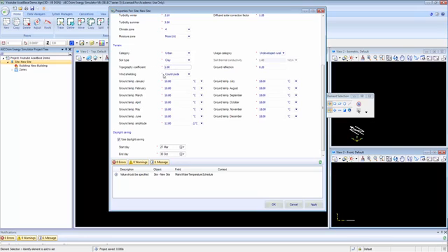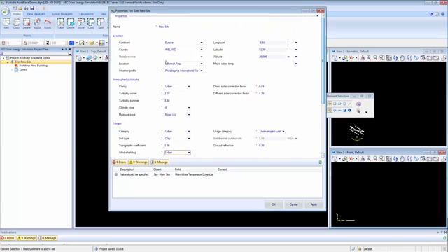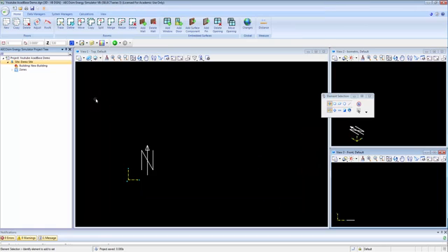Let's see, topography coefficient, wind shielding, countryside. I'm going to go for urban on that. And let's see what else we have. Daylight savings, if you want to set those as well. So there. Just a couple of quick changes there. Site, we can call this demo site, just to give it a name. So again, click apply, click OK, and now we get to that point.